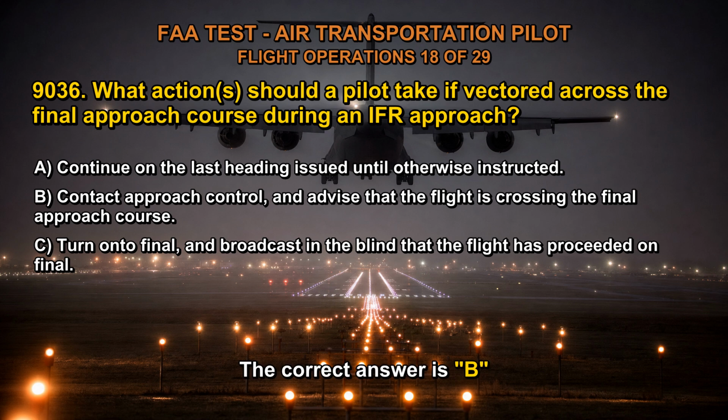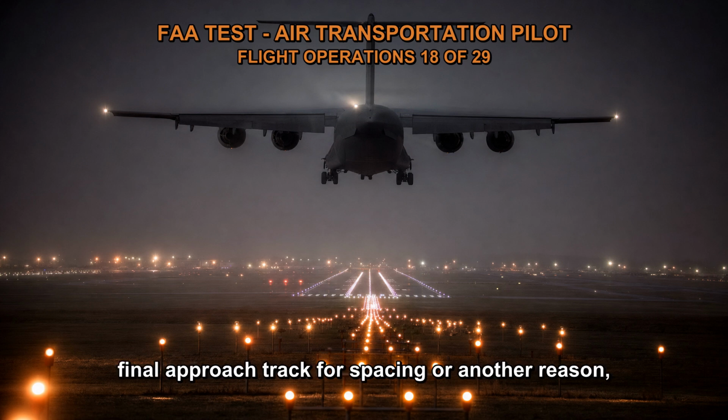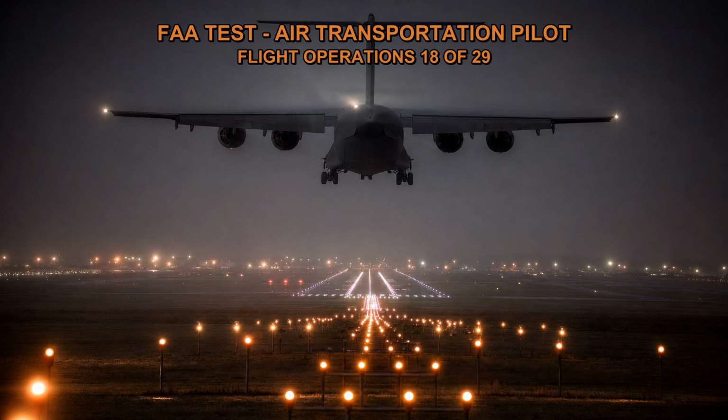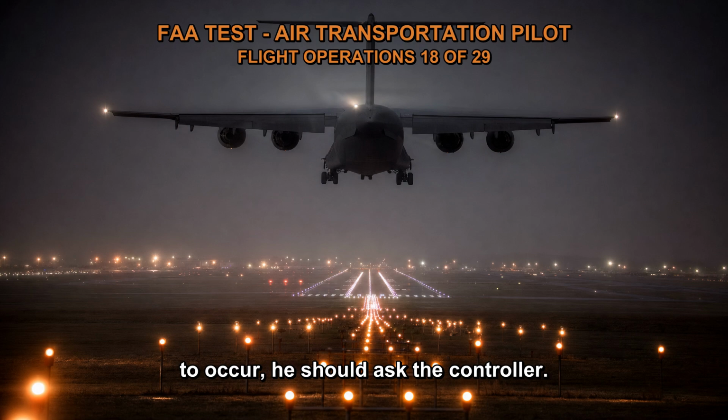The correct answer is B. When it is essential to vector over the final approach track for spacing or another reason, aircraft are typically notified. If the pilot has not been advised that he will be vectored over the final approach course and an approach course crossing is about to occur, he should ask the controller.